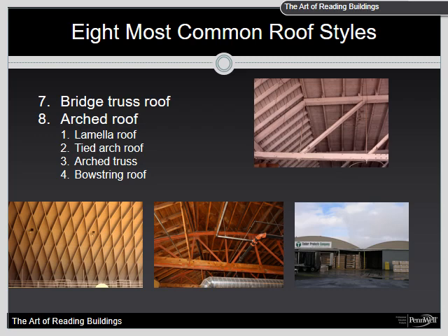Hazards. Although these roofs can offer some protection, when exposed to fire, total roof collapse may occur if fire removes more than 20% of the roof structure. In this case, total collapse of the roof can result from a domino effect. These roofs will likely have multiple layers of composition material and will be difficult to ventilate unless an aerial device is available.